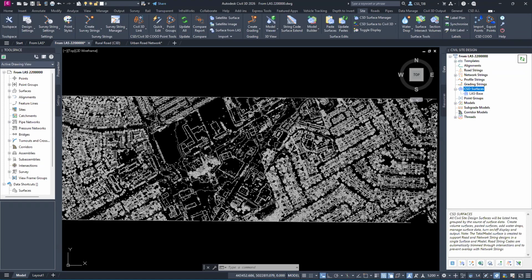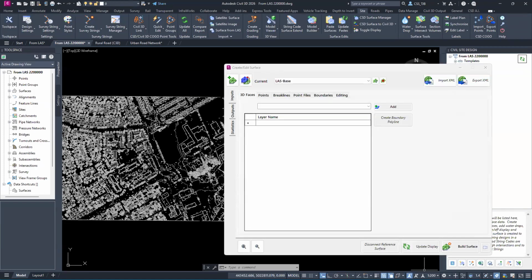So a project could contain a surface model that has a lot of points. And in this case here, it's 2.2 million or 2.2 million odd. The adaptive decimate protects the system integrity in regards to large TIN surfaces by automatically reducing their complexity. When a surface has too many points, the feature activates, dividing it into cells. Flatter cells are simplified into just four corners with an average elevation across it, drastically taking out excessive data while preserving the overall shape. Cells with greater height variations are further analyzed and refined, and the whole process maintains the integrity, manageability, and accuracy of the surface.